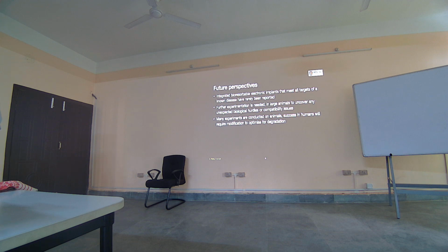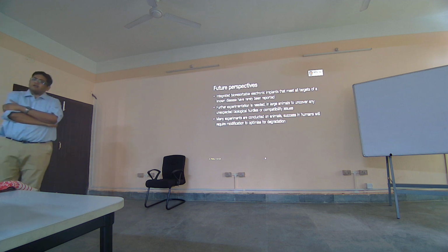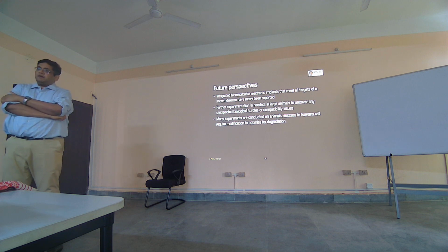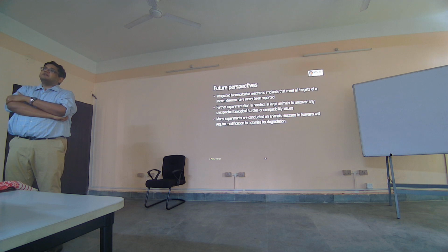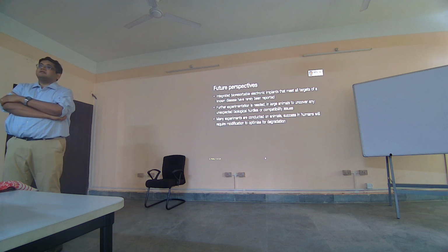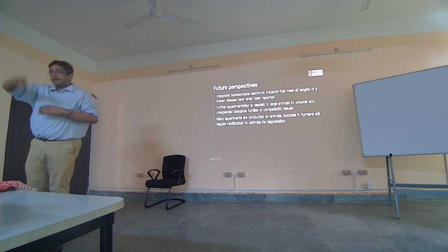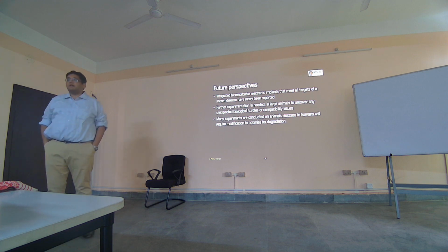Sir, what type of activation function do you use in neuromorphic design? So typically there are standard functions like sigmoid, ReLU, etc. Those are all used in software. What we do in hardware is we generally use a transistor in its sub-threshold region, below VT, to generate that, because you get that sharp nonlinearity.